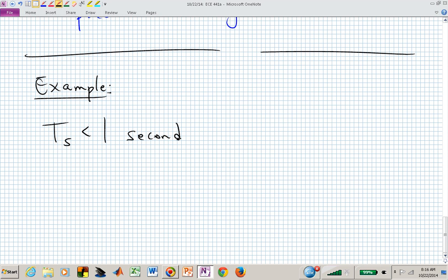And settling time corresponds to some kind of a line, and you just told me it's this vertical line. So you should be expecting now, with a settling time, let's say a 2% settling time of 4 time constants, tau is inversely proportional to the exponent in an exponential damping term. So that's the sigma. Settling time is 4 over sigma, a 2% settling time, and you now want that to be less than 1 second.